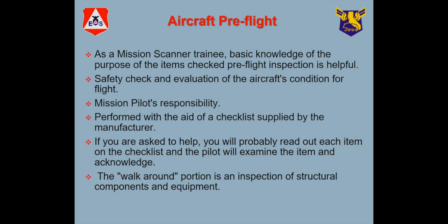But we also do a kind of pre-flight before we move the airplane, and that's when you're getting into the aircraft handling and movement training, which is a little bit different, but it's also a pre-placement inspection to make sure that you're not going to run into anything and damage the aircraft. So basically, we're looking to make sure that there's enough oil in the airplane, all the control surfaces work correctly, so that when you turn the yoke to the left, you get the right response with the ailerons. When you step on the right rudder pedal, the rudder moves in the correct direction.